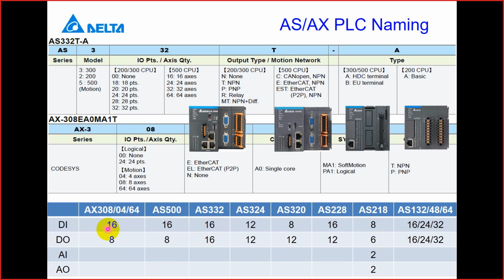So here you will find that for Delta PLC rule, at least we will have 8 input. I mean, for the input, we'll always follow the, you can say the old traditional way, as I mentioned at the last section, like X0 to X7, we will always have 8, at least 8. But for the output, the number will be different. So you can see like 12, like 6.